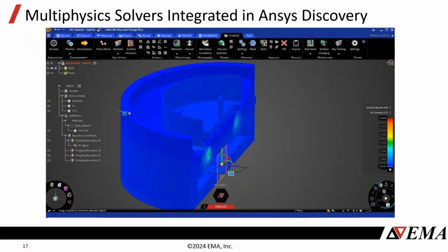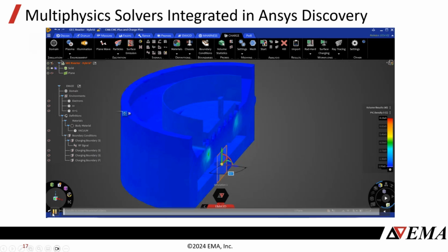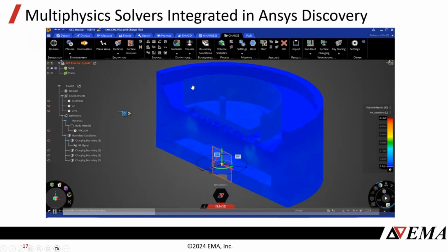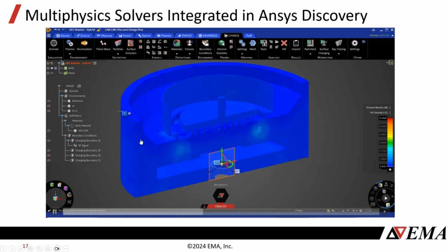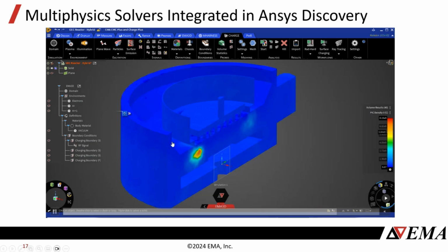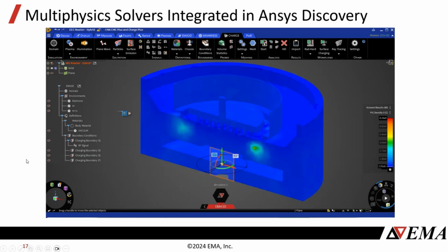And then if you want to add an RF source, we can do this. In this case, this is an example of the same chamber, that same vacuum, where we generated an argon gas, and we are able to apply a signal to the system, in this case, an RF signal. And we have also an emission model that is present and available from one of the tools up there to be able to understand if electrons are going to be emitted when the fields are too high. So in this case, we reached values for electromagnetic fields that were high enough to create E-field emission and generate electrons inside the system.